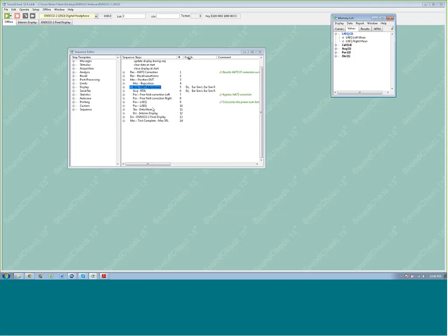Once you have that configuration, the sequence can play directly out of the digital headphone signal path. It performs the test very similarly to the -1 part of the standard, actually. It plays the stimulus file through the signal generators at a level of -10 dB full scale, and then it's going to check the output on the RTA and give you the 3rd octave spectra that get corrected, and then we'll look at the total sound pressure level averaged over the 5 trials. So sort of a hybrid between the -1 and the -2 analog headphone portion.